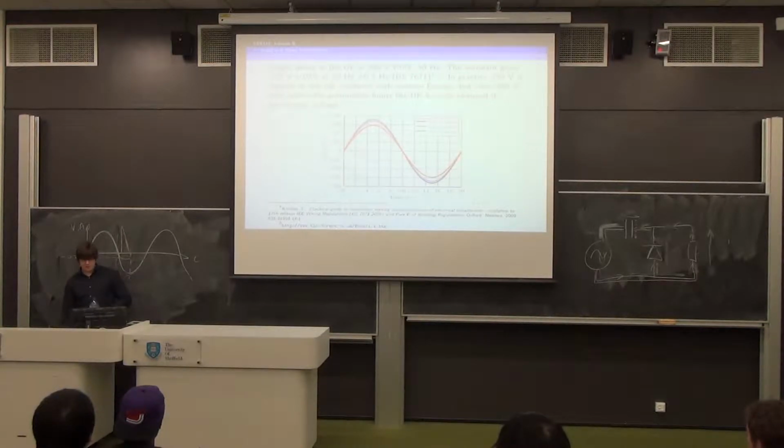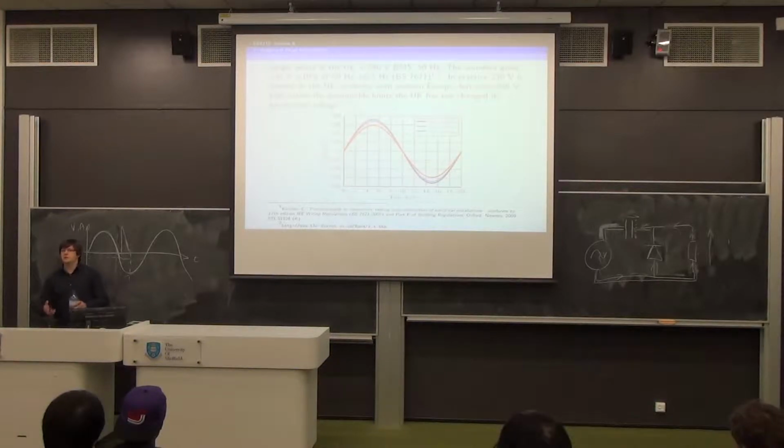The specification for frequency is plus minus half a hertz. The reason it's quite a tight spec is some clocks run off it, but that's neither here nor there. If you lower the frequency too much, and you've got some electrical machine, and you've designed your machine quite carefully, the flux is proportional to the current that's flowing in the turns, which induces the B field in the magnetic components.